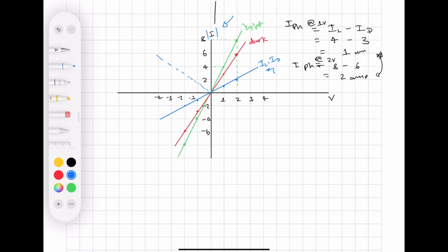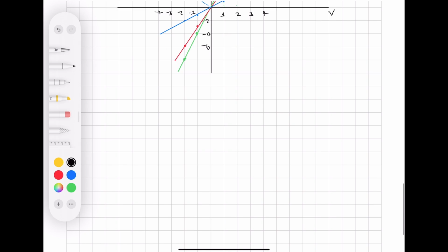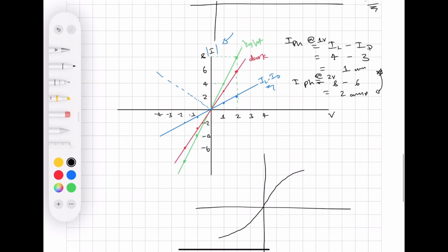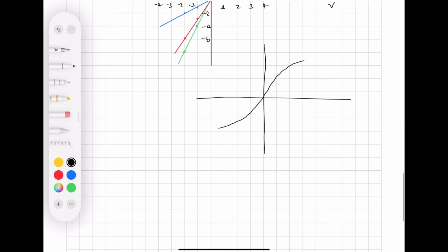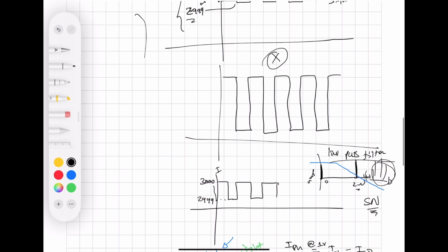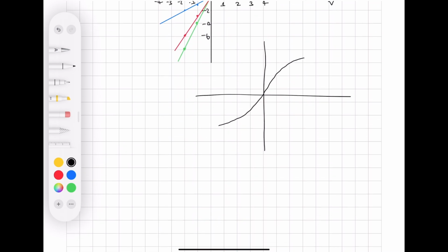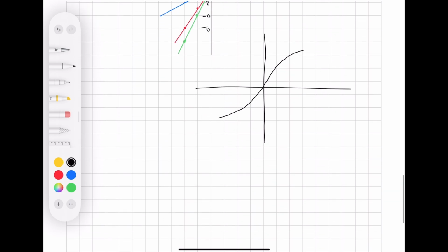It gets more complicated when we have non-ohmic contact. When you have a Schottky contact, your initial current is going to look more S-shaped, and we'll talk in a future video why that is. When that happens, this step with the lock-in amplifier becomes less powerful. It still works, but it becomes less powerful. We'll talk about that in the next video, and also the case for diodes, and similarly Schottky diodes. Thanks for watching.